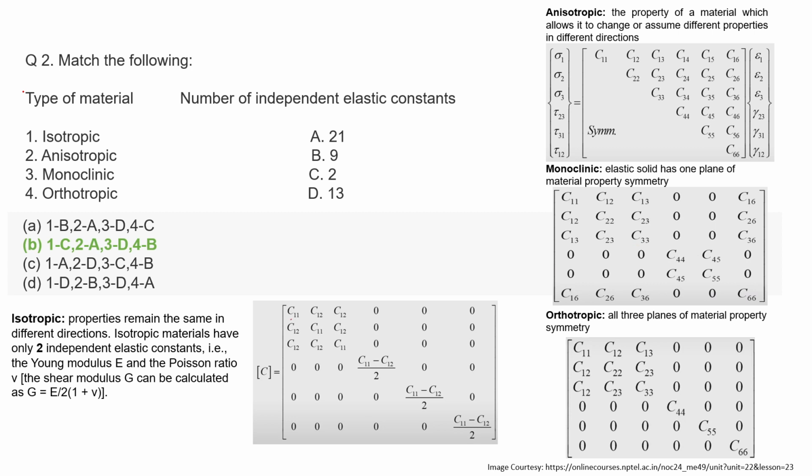After that came the concept of symmetry, that the constants, like the one in direction 1 3, will be equal to the constant value in direction 3 1. So from the concept of symmetry, the number of independent constants reduced to 21.